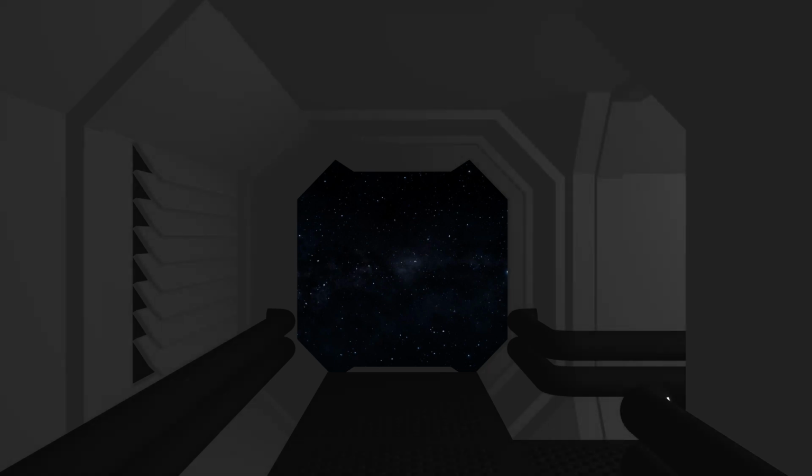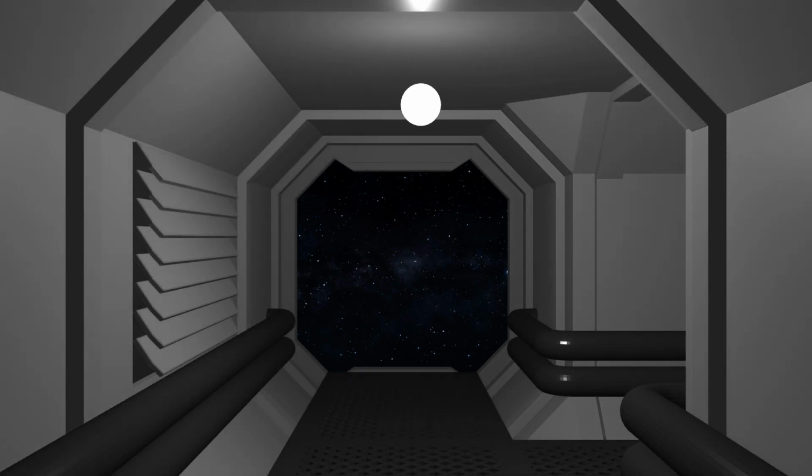First, there is the ambient light, representing light that has been scattered or bounced off surfaces rather than emanating directly from the source. It's used to simulate the overall environmental illumination. Ambient light alone might not be sufficient unless you're aiming for a dark environment, as it primarily outlines objects in your scene. For a more realistic touch, consider using a point light in addition to ambient light.